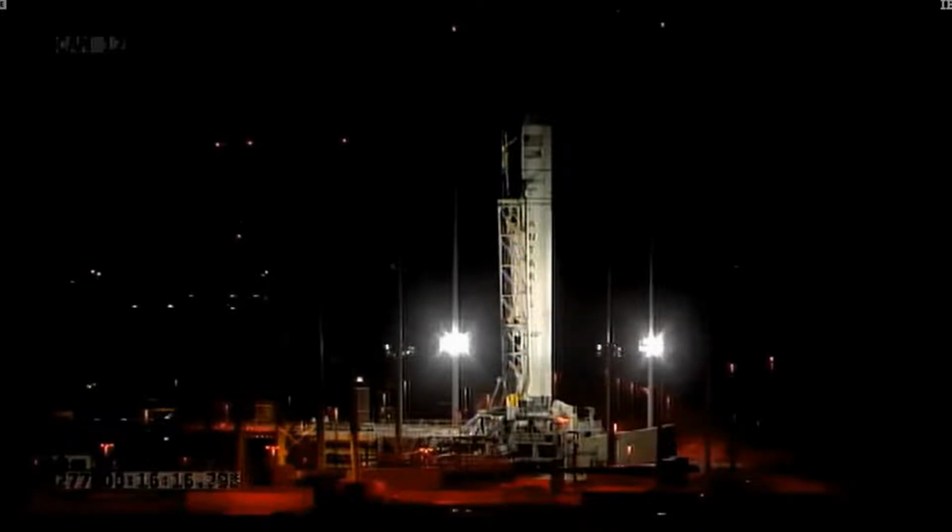Launch team, LC, countdown 1, passing through T-minus 1 hour to our target T0. We are currently in our core high flow RP loading and our core high flow LO2 chill down. Next milestone will be at 56 minutes from T0, where we will transition and start a core low flow LO2 loading.